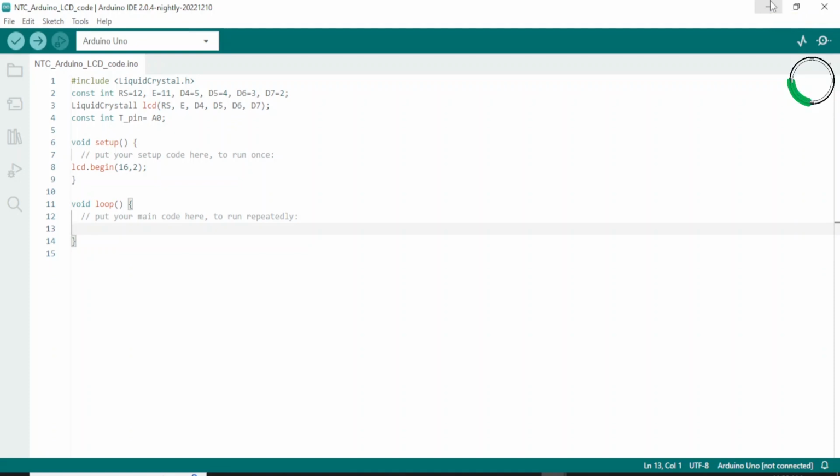To do so, read the analog value from the analog pin of the microcontroller by just writing V voltage, or just say V0 = analogRead(Tpin), semicolon. V0 needs to be declared as an integer value, int V0. Program our microcontroller to write what has been read to the LCD. Don't forget to save your code to an appropriate folder.